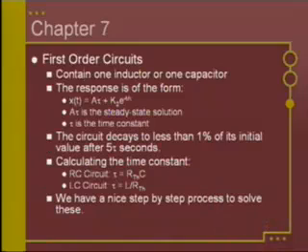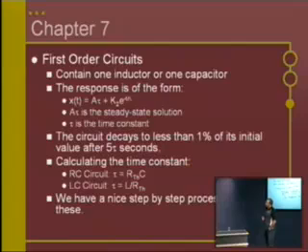But in chapter 7, we looked at first and second order circuits. There's a lot of stuff on here on exactly what the problem solving technique is. You can go ahead and review that, make sure you're comfortable with it. We just did an example at the beginning of class. Draw the circuit at time equals 0 minus, with this idea that it's been there for long enough, and so the storage element has assumed its steady state condition. Then solve for the voltage across the capacitor or the current through the inductor.